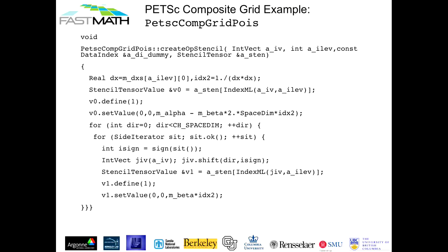If you actually take your operator that would move you forward once in time, build the matrix for it, and look at its spectra, you will see things like, well, the third eigenterm in that system is negative or much larger than 1. Then I have a stencil that reaches out at least 2 or 3 cells that has the wrong coefficient, the wrong sign on it, right? Or are you expecting the system to be symmetric? Did you think you were building a symmetric system? You look at the matrix and it's not symmetric. Well, now you have a clue. Now you can go back and start looking at your operators and see which of these little sub-stencils was starting to get non-symmetric.